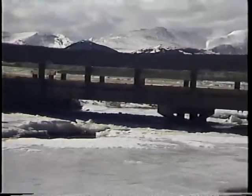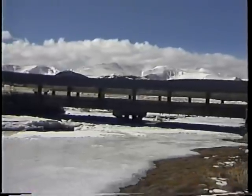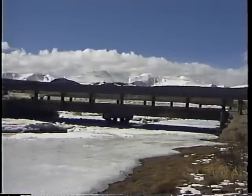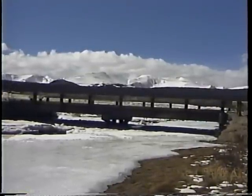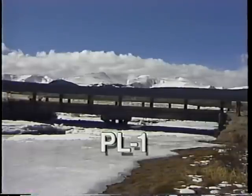Light passenger car and light truck traffic is common on many rural bridges. Requiring a high-performance bridge railing on a low-volume, low-speed bridge is not generally cost-effective since both the probability and likely severity of an accident is low. Some rural bridges fall into the first performance level category, PL1.